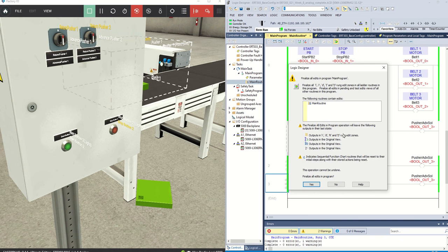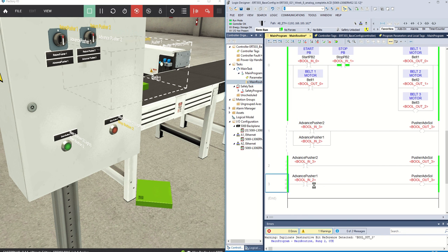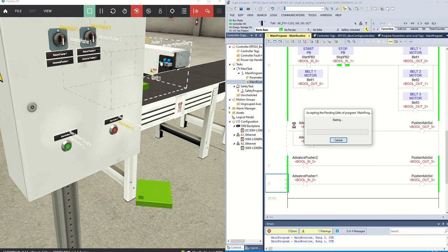So you're making an OR condition. Really what you want to say is that if this input is on or if this input is on, turn on the output. Because that is really the condition you're trying to create here. But you can't do it on two separate lines of logic. It has to be combined into only one line.